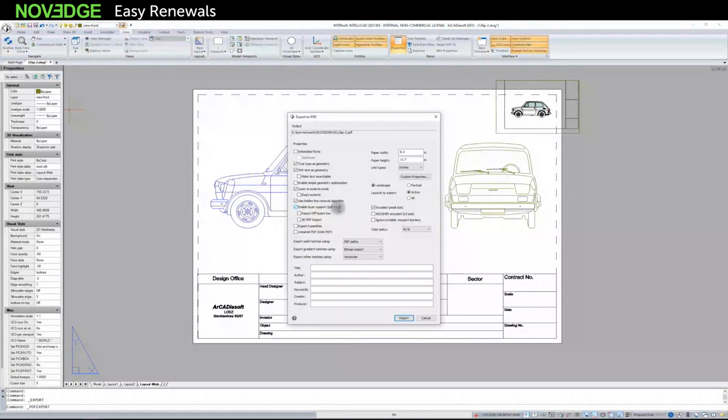However, when printing to PDF directly, we don't have this ability to define layers. Only during export, in the window that I showed in the previous presentation, we can enable layer support for PDF prints. If we have more than one sheet in the project, then we can export either just the active sheet or all sheets together. They will be exported into a single document, with each sheet following one after another, creating a comprehensive file containing our entire project if needed.